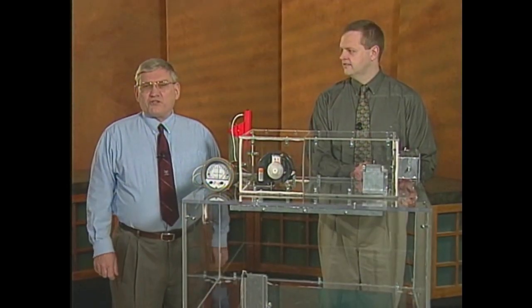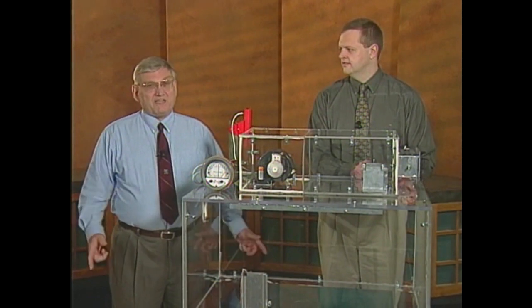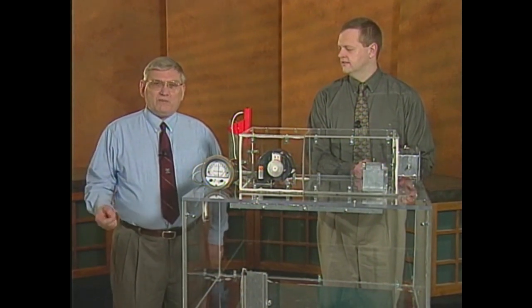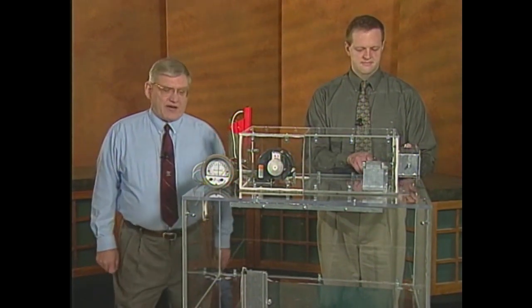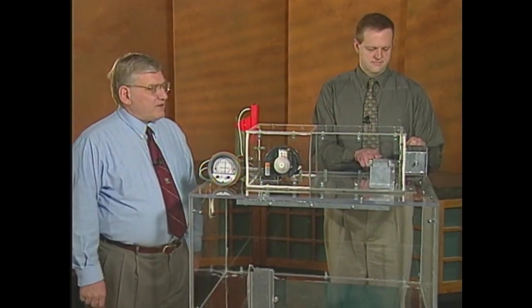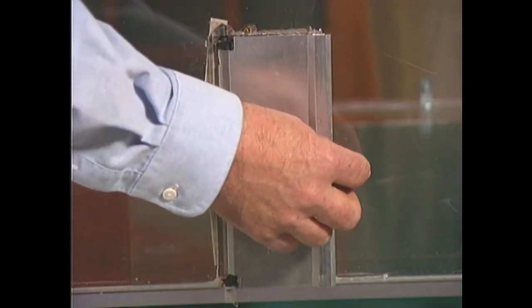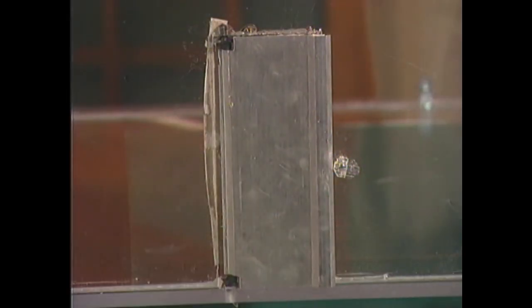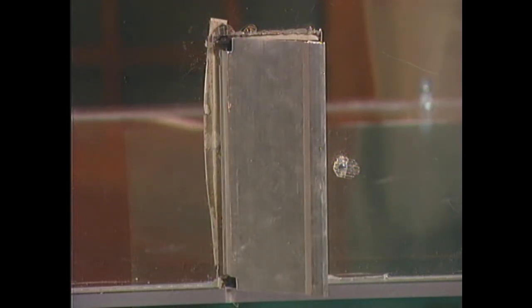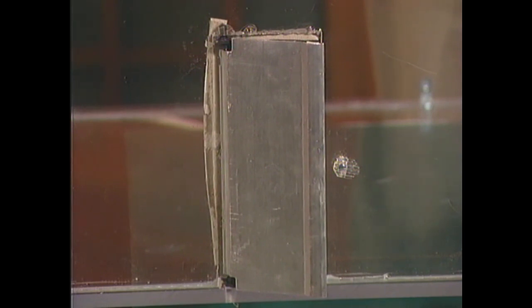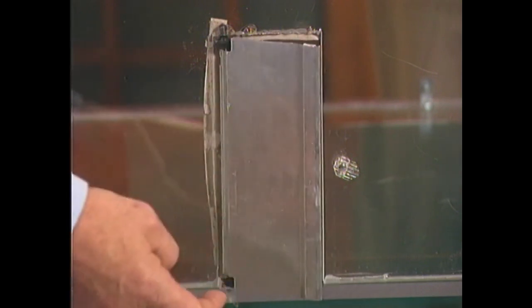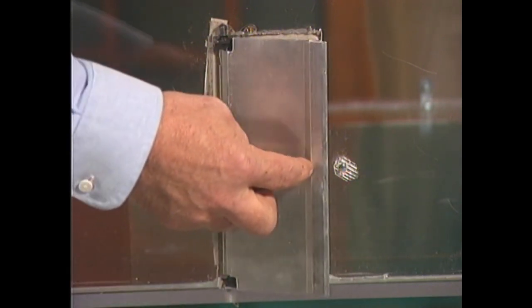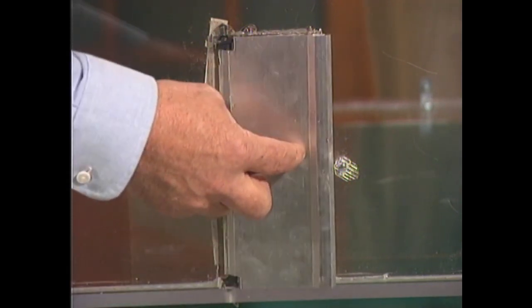John talked about overpressure issues in a building with natural relief, and we can demonstrate that with our model. In a real building, doors would typically be in use, and we can demonstrate what happens when the doors are activated. John, throttle the outside air back to 0, and I'm going to unlatch the door on the front of the building. Now, when the outside air is increased to the space, boom, you'll see the little door literally pop open. In fact, this door is very hard to close. If I go up to it and push the door closed, I'd have to push it closed hard enough to let it latch against the lock.